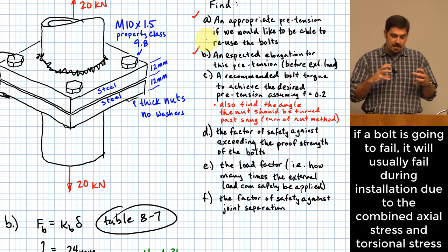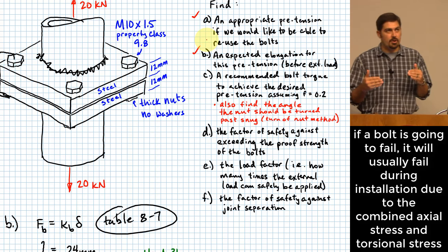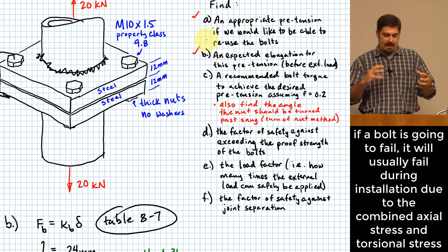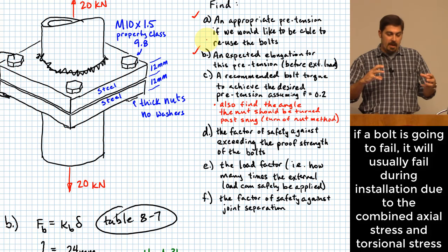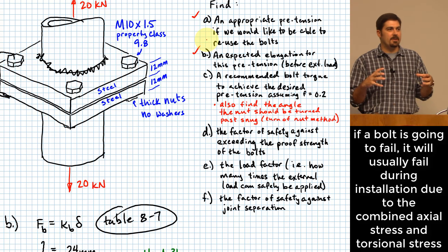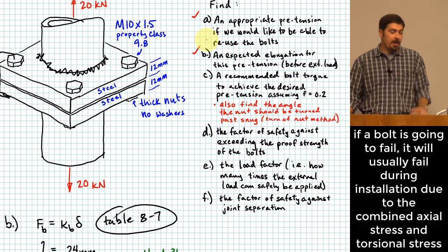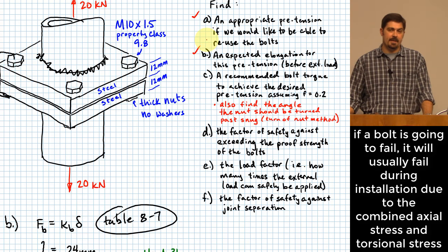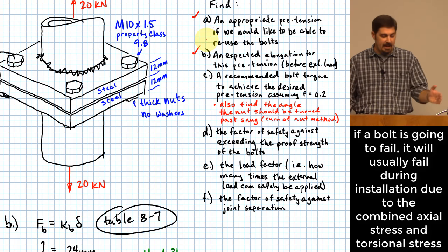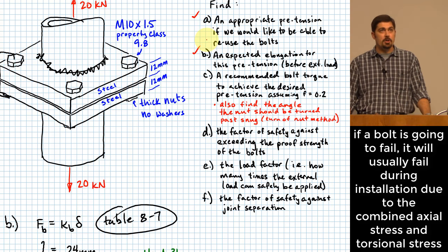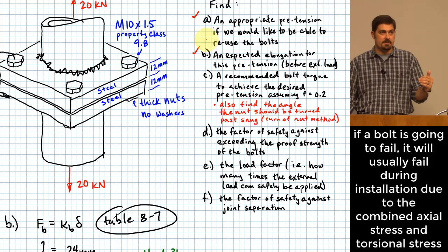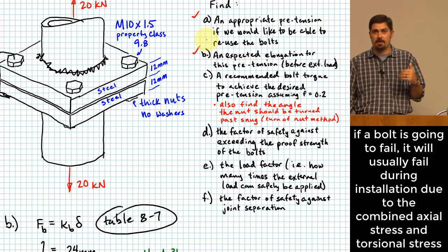Now the thing is, this is kind of good and bad. One of the good things about that is that it makes you more prone to break your fastener while you are installing it, because you're putting extra stress in there that you hadn't necessarily accounted for. But that's actually not really a bad thing, because if the fastener's going to break, it'd be good to break it while you're installing it rather than having it break in service. Would you agree with that? If it's going to break, it's probably better to break it beforehand rather than later.